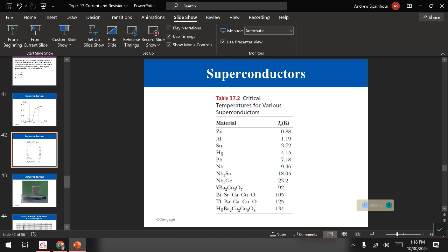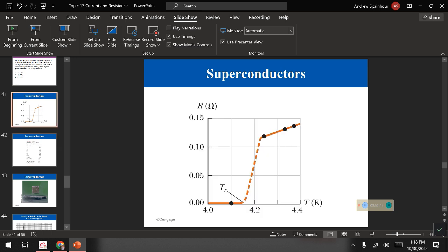All right, back to the conductor thing. So we work our way back down, we get resistances that are smaller and smaller and smaller. The interesting thing that they've found is this graph right here, that at a particular temperature, and please note, by the way, the scale, they don't present this very well. That's 4, that's 4.2, that's 4.4 Kelvin. All right, so cold. You're dropping. They found that this guy right here actually takes a steep drop off at a particular point, and this is what they call a critical temperature. A critical temperature is for a material where at this temperature, there's 0 resistance.